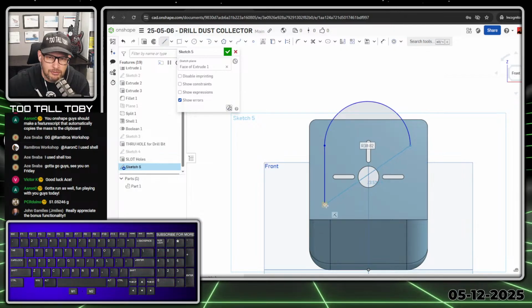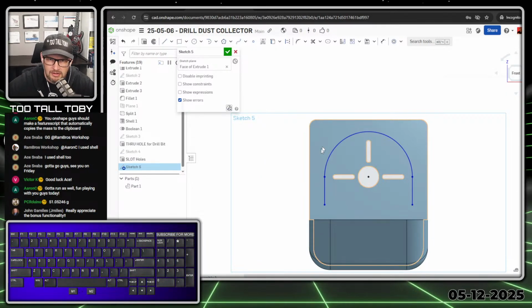If you just take your mouse over this point, then that lets you wake up that horizontal relationship. So that way we can get over there and we can wake up that horizontal relationship. And it actually does apply the horizontal relationship. So you'll see here, I take this point and this here, Shift O, that's your concentric.